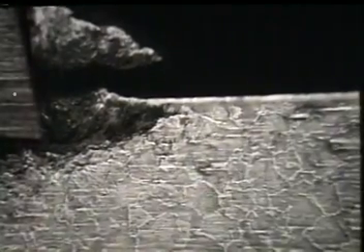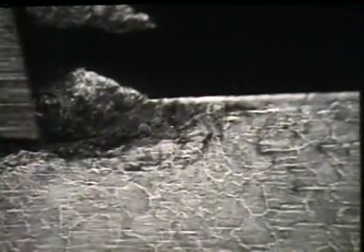To observe the chip formation of a higher carbon steel, a specimen of annealed 1060 steel is machined. The microstructure can be seen beneath the tool and outside the plastically deformed zone. The microstructure consists of fairly large grains of pearlite surrounded by a network of ferrite. The pearlite grains appear gray and the ferrite is light. The ratio of the amount of pearlite to the amount of ferrite is opposite to the ratio of these 2 structures in a 1020 steel.